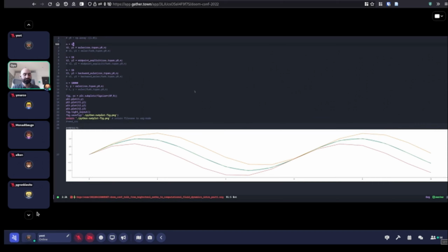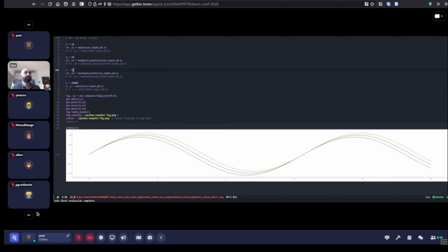And if we increase these points now a bit, so instead of 15, let's take, I don't know, 50, and change this one to 50 as well, and change this one to 50 as well. So if we do something like this, we run it again, starting to look better. The midpoint actually sits so close to the Euler, which is using 10,000 points, which is quite ridiculous, because with 50 points, we get as good a solution as here we get with a lot more points.